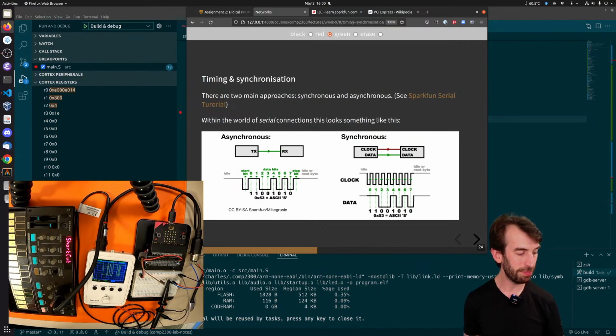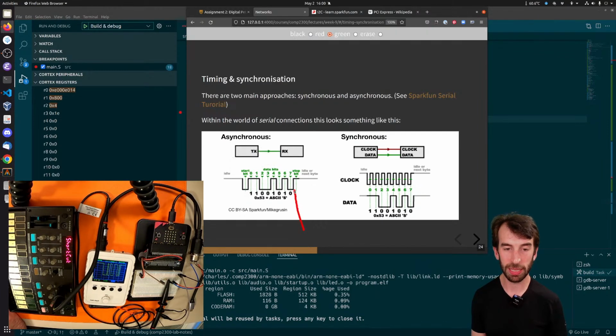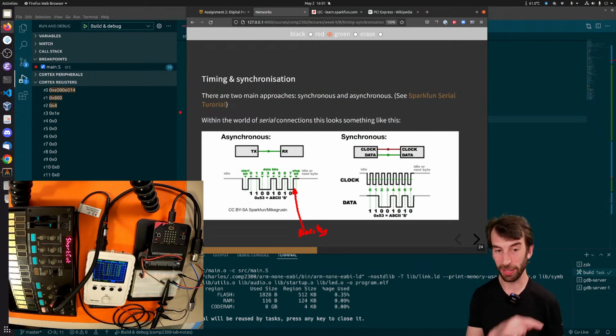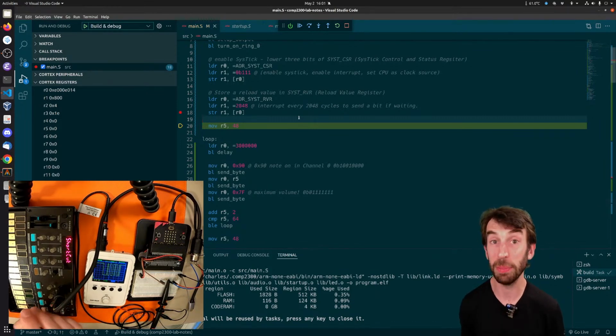You have to just follow the instructions with these things. It's part of the protocol. There are actually other aspects of this which I haven't done. There can be another bit in there which is called the parity bit, which is a little bit of error correction. It lets you know if the byte has been received correctly. The parity bit is like the oddness or the evenness of the byte which has just been received, of the addition of all of its numbers. So that can give you some indication about whether your message was correct or not, but we don't need it for MIDI, so I'm not going to deal with it.